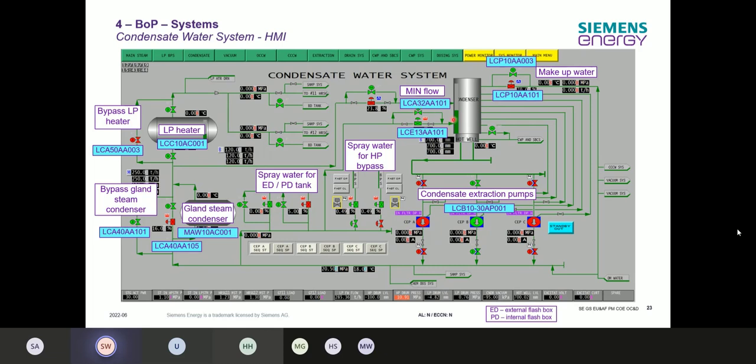So these are controlled lines for the MinFlow. But as soon as the outlet is open, you have a certain flow to the outside to the two boilers, then these lines will of course be closed, and they will just open up again when there's no flow at all anymore.